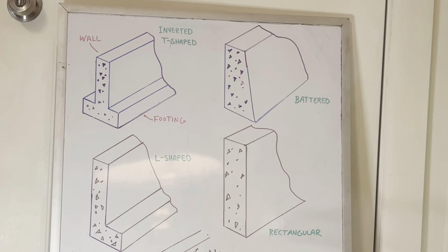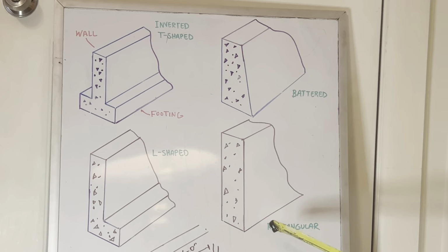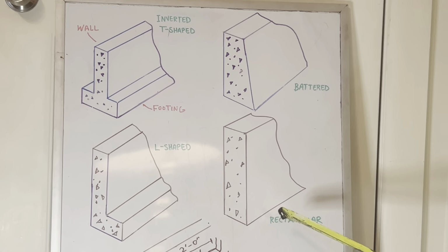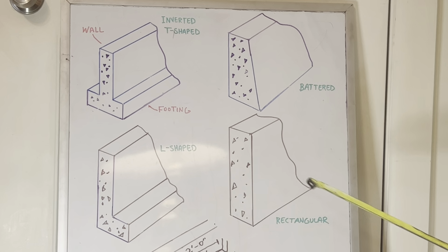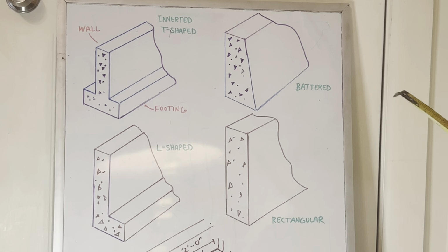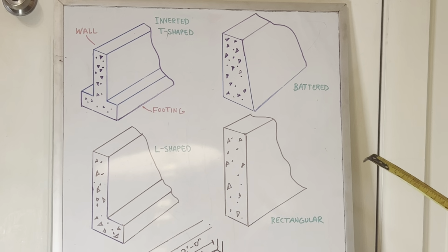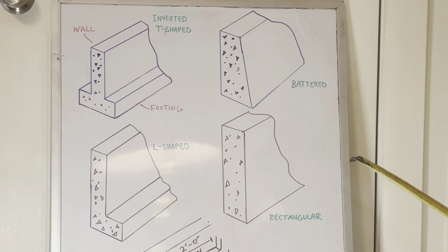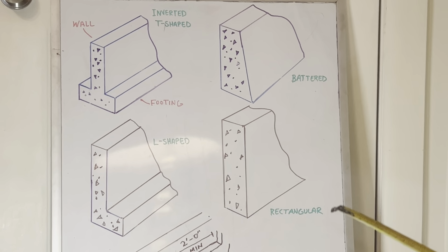However, like I just mentioned, with these rectangular foundations, you need to have basically a light load. You got to have stable soil conditions in order for this to work. I mentioned before how depending on what type of soil you have, that's the type of foundation you're going to have, okay?